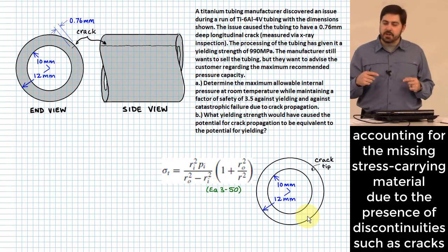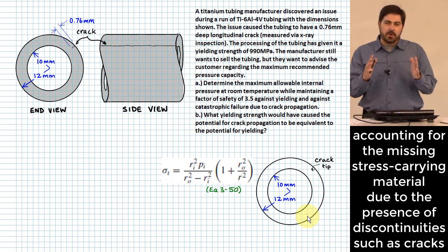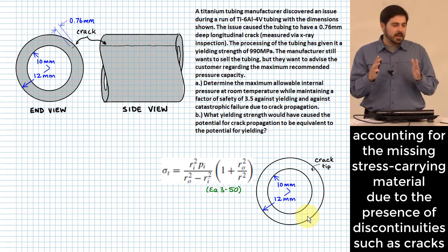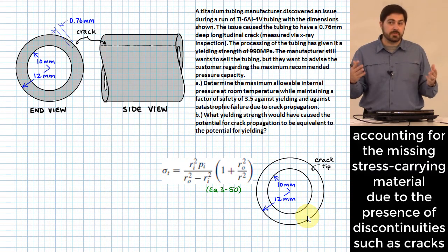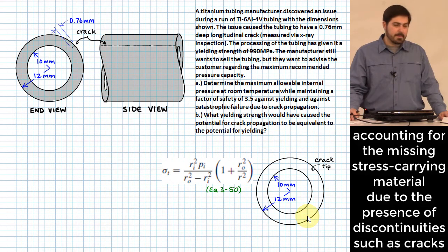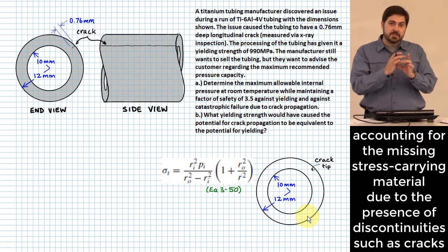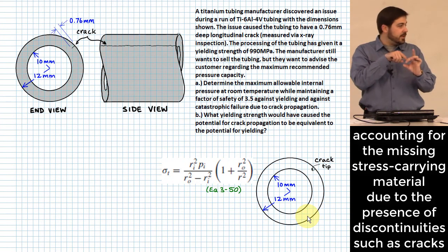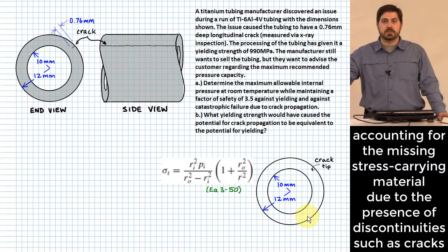When you calculated the nominal stress and you have this hole in the middle of a plate, what area did you use to calculate the nominal stress? In other words, the stress that you would have calculated before having the stress concentration. Yeah, so you would basically look at the plate and subtract the cross-sectional area that's gone because there's a hole in it, and you would use that as your nominal stress before even calculating a stress concentration factor.